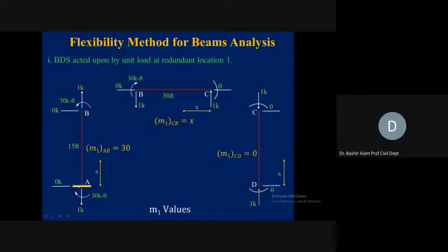We need to keep this AB member in equilibrium now, so 1 kip in the upward direction, so 1 kip in the downward direction at A. Horizontal is 0. 30 is counterclockwise, so 30 clockwise here at joint B. So joint B is also analyzed and is in equilibrium.